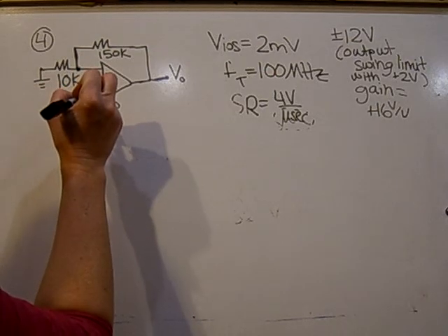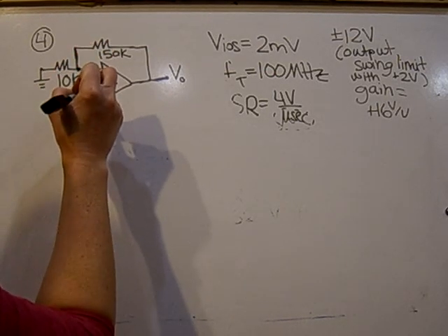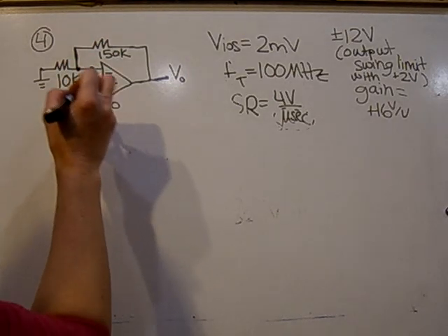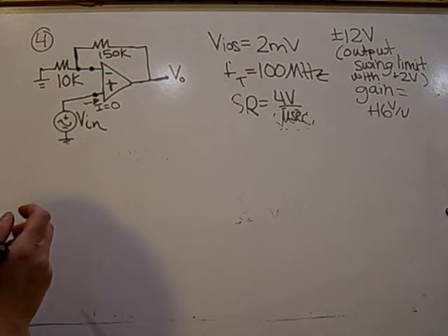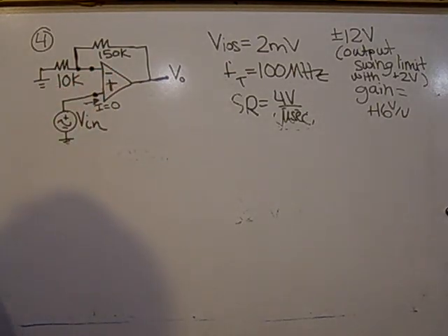So to compensate for that, what I want to do is take the resistance to be the same at each input node. Therefore, the input bias currents will be approximately the same. That I times R will be a common value on each one and therefore cancel out.